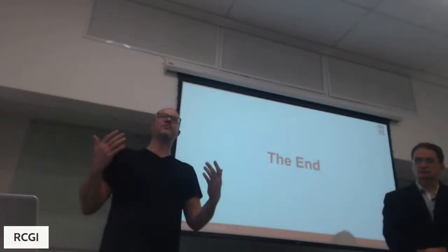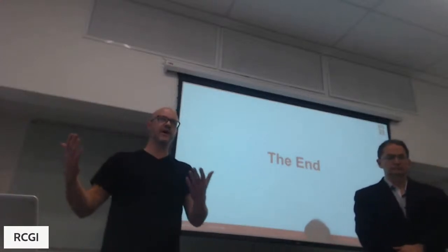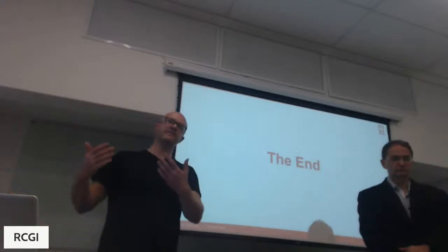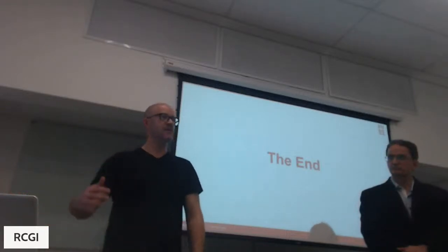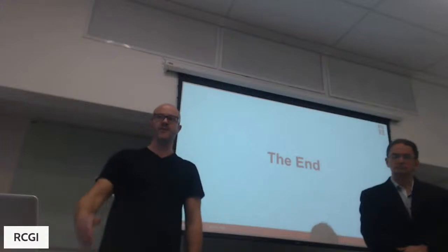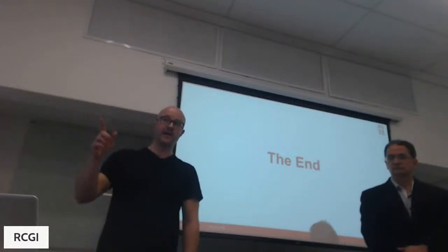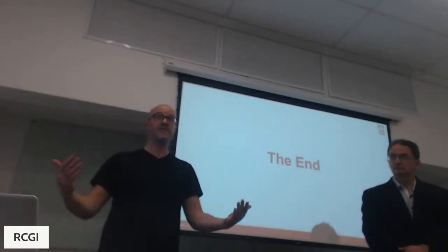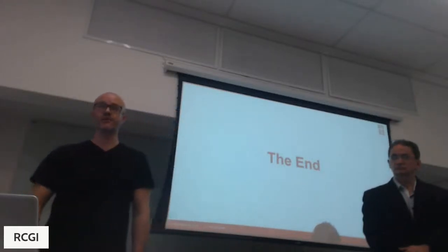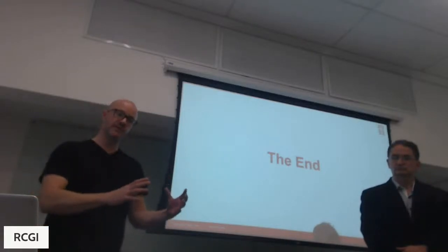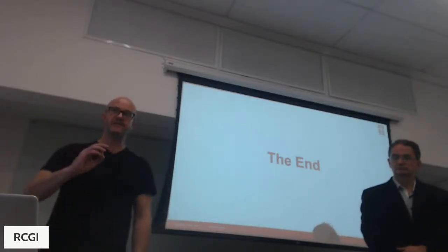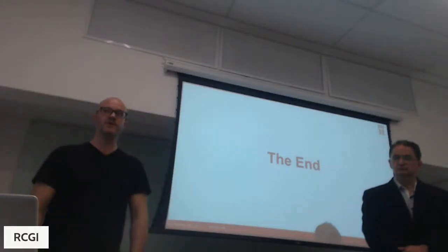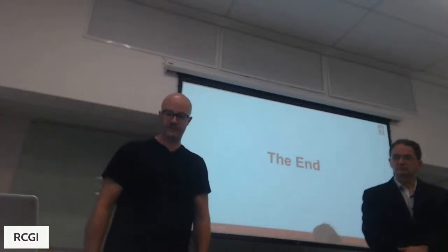But I would put it like this: every optimization task requires its own tool. The SIMP method is good for something; it's not good for everything. And therefore, we use a combination of level sets and cut finite elements to do these kinds of coupled physics problems, where you have nice geometry, you can impose it. And a comment about genetic algorithms, I'm sorry to say so, but it's a no. It simply doesn't make sense to work with genetic algorithms unless you have a very small design space and your function evaluations take a fraction of a millisecond. If you need to solve a PDE, you're going to be a very old person before you get results.